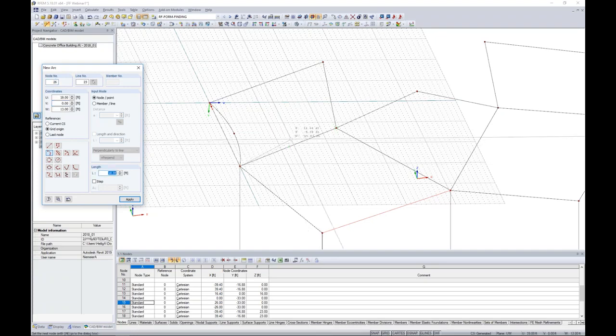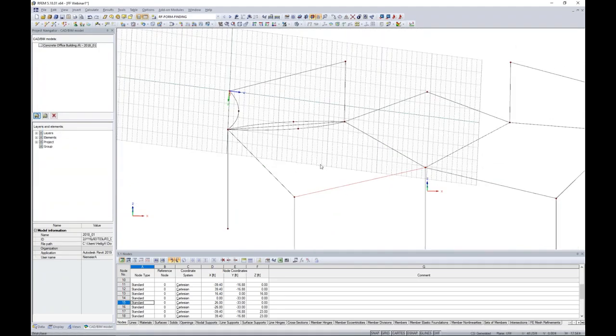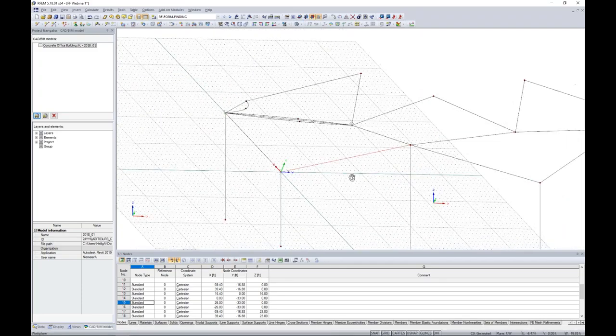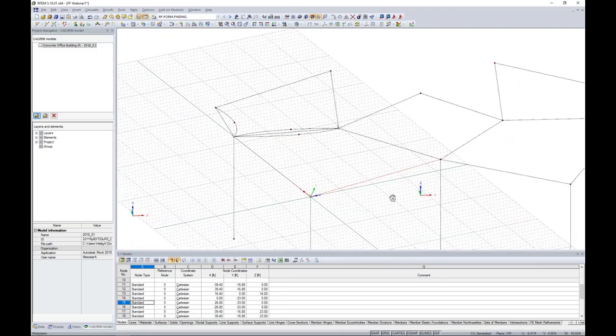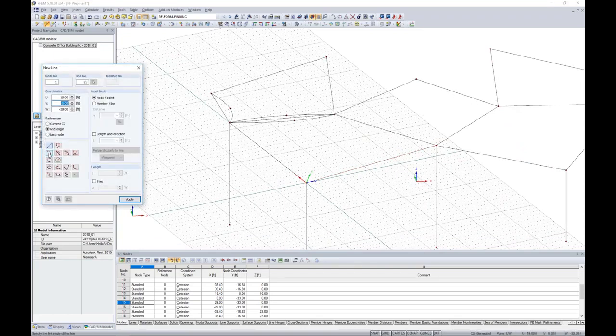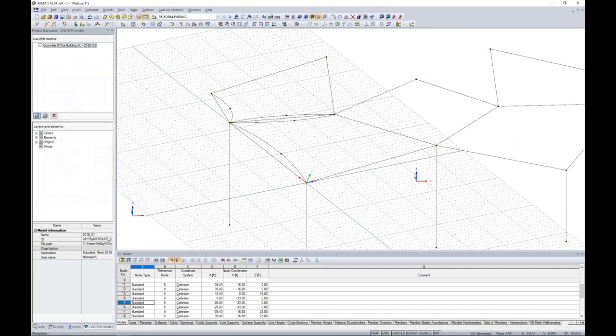So I'm going to do the same thing at a different location here for my cell points. Again, completely arbitrary. We need to move up to the second cell and we need to change our user-defined drawing grid. So I click first to reset the drawing grid, click it again to define my new point, and I can click on 3 points here. And now you'll notice that I have a new drawing grid at a specified angle. So we go to draw a new angle here with the given arc, and I can simply snap to these points. Again, any arbitrary points.